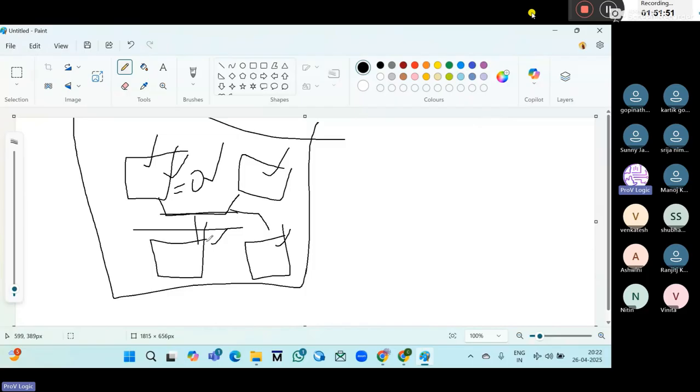What is the difference if you use it without HMASTLOCK? Suppose the CPU is reading and another master is writing, then the data becomes wrong. If you use master lock, after the CPU completes its read, it modifies, and then the next IP will write the data, so no other master will interrupt. Clear everyone? HMASTLOCK is simply "do not disturb me." The CPU is telling that it is busy. That is HMASTLOCK.